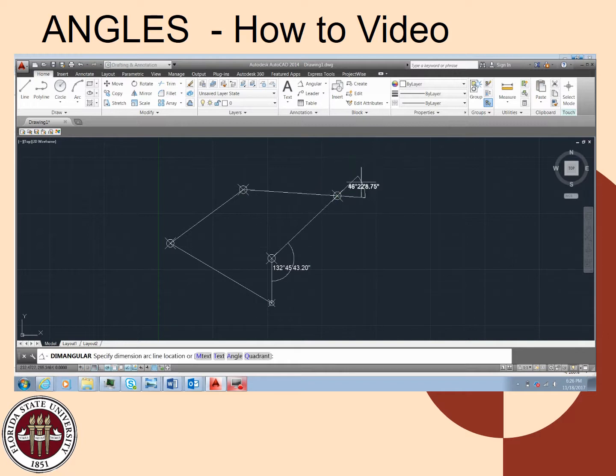And one thing you notice about AutoCAD is it doesn't like to go outside of 180 degrees. In this case, 133. I'm going to also dimension the acute side of it. Same for this angle. Again, angular dimension. I'm going to leave these up here for a little bit.